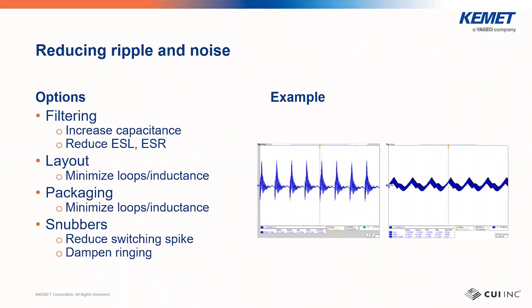The ESR, like ESL, is also influenced by the package and layout. Reducing lead length and minimizing the loop created by the layout will help reduce the ESR and ESL effects.